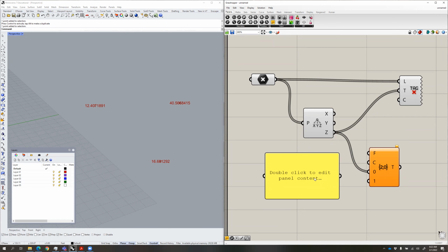And we're going to write into this panel here a little format logic for how we want these spot elevations to be displayed on the screen. So what I mean by that is just follow along here. I'm going to put in a little bracket, the little squiggle bracket you see there. And then I'm going to type in 0, because 0 is the number that the Z is being input here.